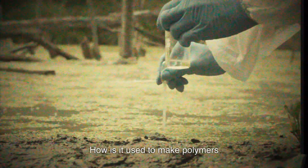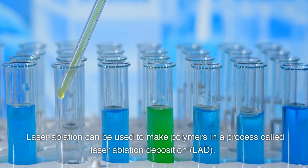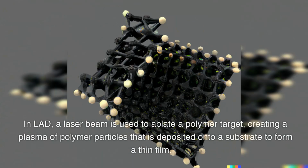How is it used to make polymers? Laser ablation can be used to make polymers in a process called laser ablation deposition, LAD. In LAD, a laser beam is used to ablate a polymer target, creating a plasma of polymer particles that is deposited onto a substrate to form a thin film.